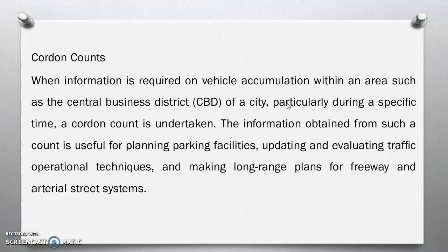Cordon counts. When information is required on vehicle accumulation within an area such as the central business district of a city, particularly during a specific time, a cordon count is undertaken. The information obtained from such a count is useful for planning parking facilities, updating and evaluating traffic operational techniques, and making long-range plans for freeway and arterial street systems.